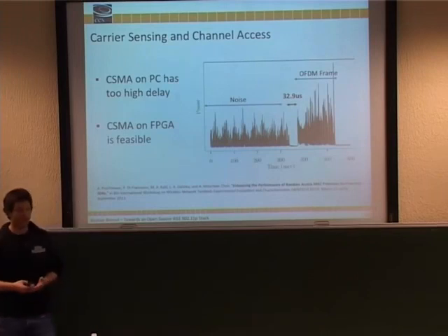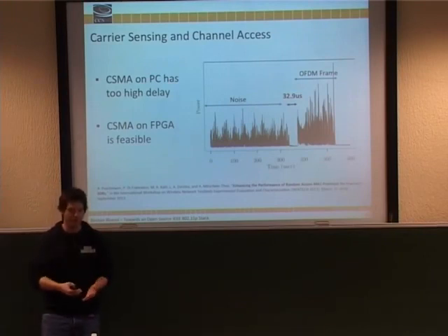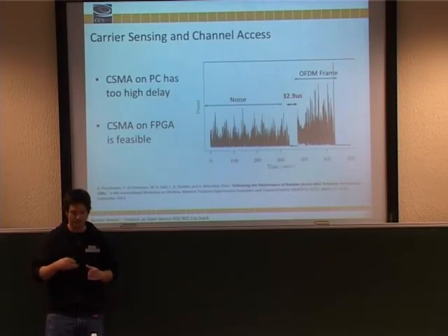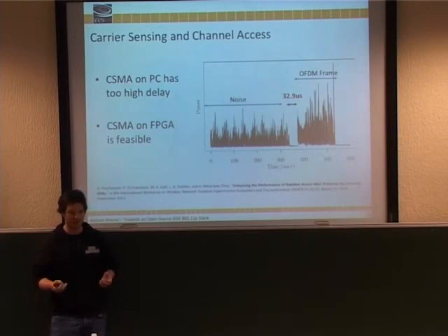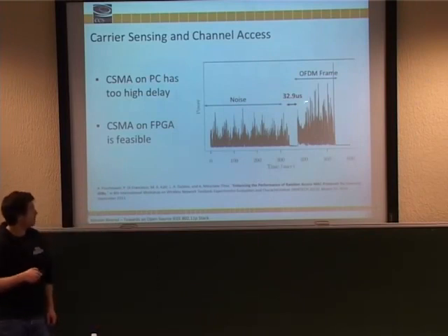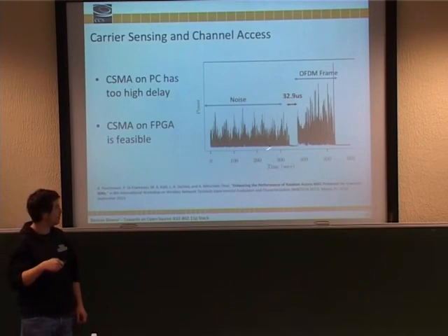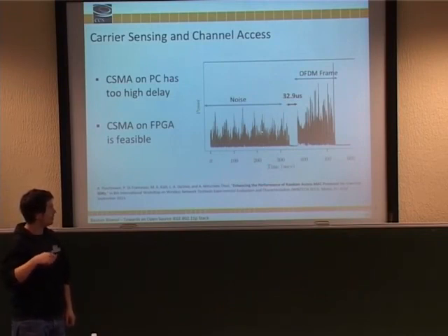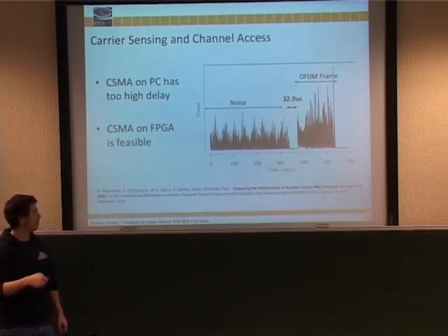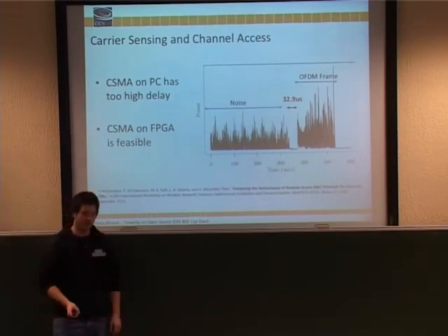What we are currently doing is that you can preload your Wi-Fi frame on the FPGA of the USRP, and then the USRP is doing channel sensing for you. It has an easy state machine. You can annotate, for example, slot times and all of that. And then you really can come down to the microsecond scale. In the example I plotted here, it's just the power levels. We had one USRP that was generating noise, then we switched it off. Another USRP, which was sensing the channel, then added a very small gap that you would not be able to manage on the CPU, and then sent out the actual OFDM frame, and we also received this frame with another Wi-Fi card.